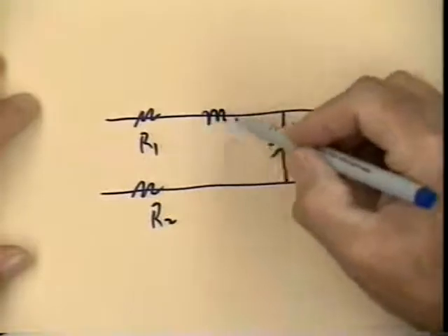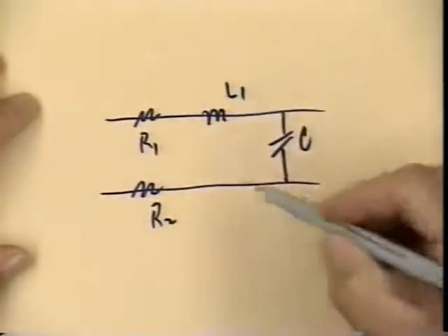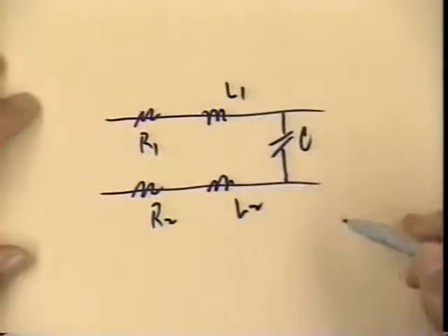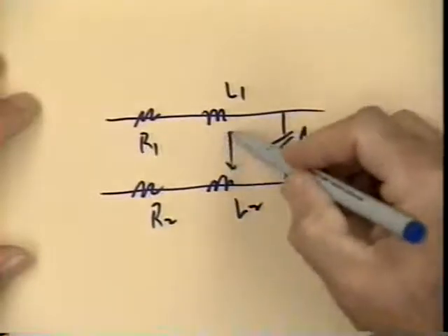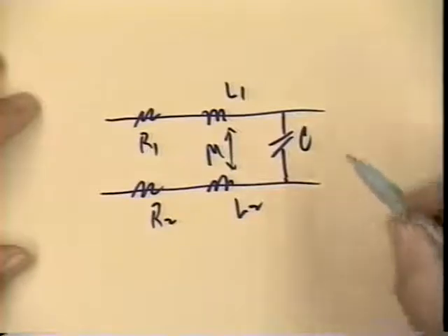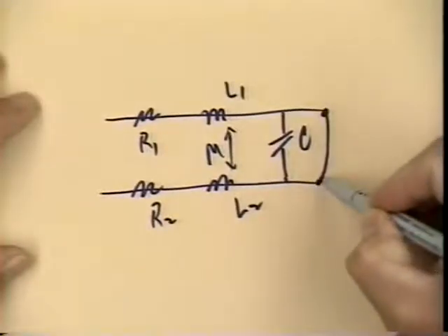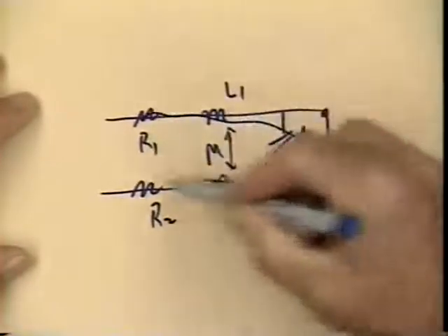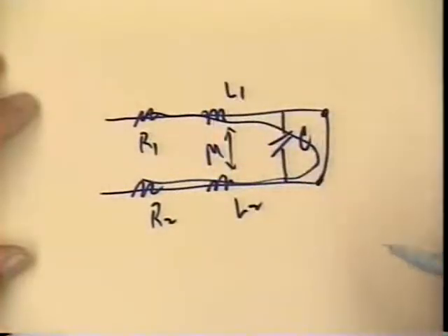They say the top wire has self-inductance L1. The bottom wire, they say, has self-inductance L2. And between the two wires, they would say there's mutual inductance M. I don't believe that's the case. Self-inductance is a property of a closed path. And in this situation here, if we were to short these two wires together, we would have one loop. One loop, one closed path, we would have one self-inductance, not really two self-inductances with a mutual inductance between them.